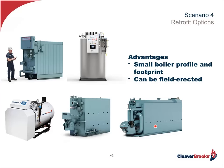But if it's a process load that's over 15 pound steam, then the cast iron won't work. It can come in sections, be built right there in the boiler room, but 15 pound is its limit. So if we've got any pressure over 15 pounds, cast iron will not be applicable. But a flex tube would, or an O-type water tube would, or this vertical would, or this horizontal fire tube would. So think about that, because then in the wintertime, that large process boiler is operating at the sweet spot all the time. And then in the summertime, the smaller summertime boiler is operating at the sweet spot, saving bundles of dough as far as operating cost is concerned.